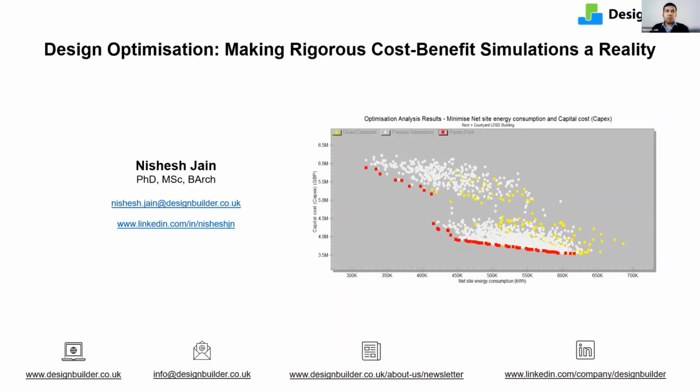You can use natural ventilation control temperatures or size of the opening, etc., for natural ventilation to come in as design variables, and you don't need to use any scripts. They are predefined variables already available to do those, and you can have your comfort and energy as the two parameters. So yes, that is possible.